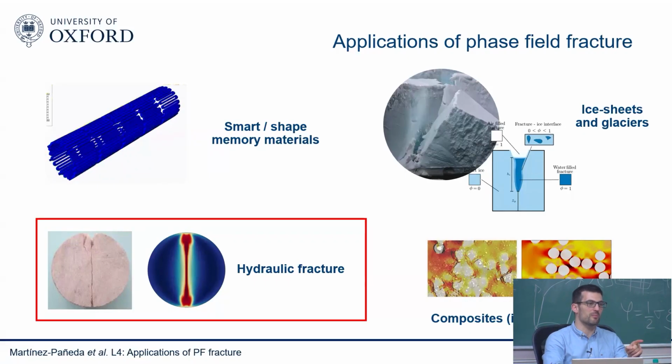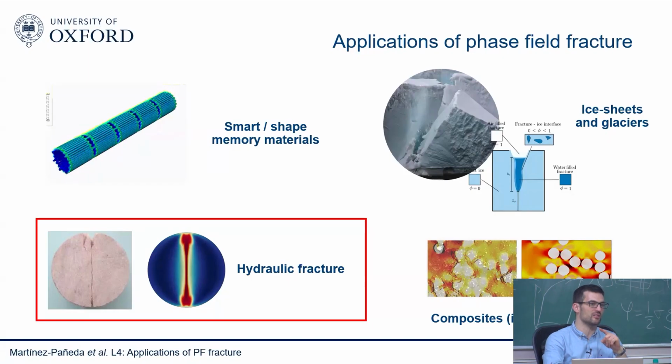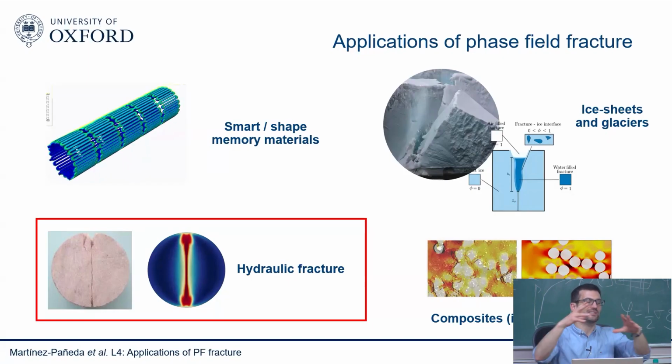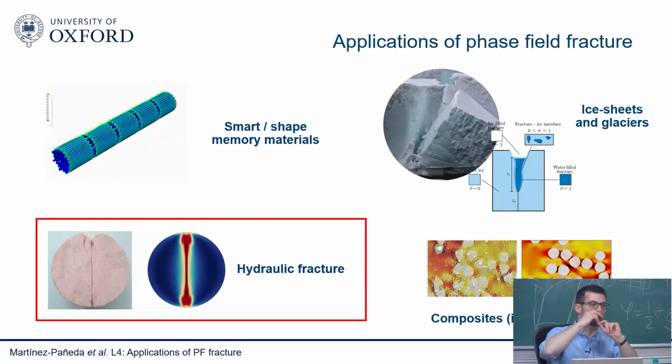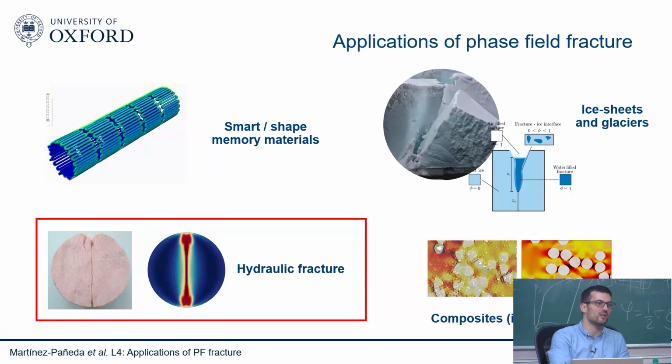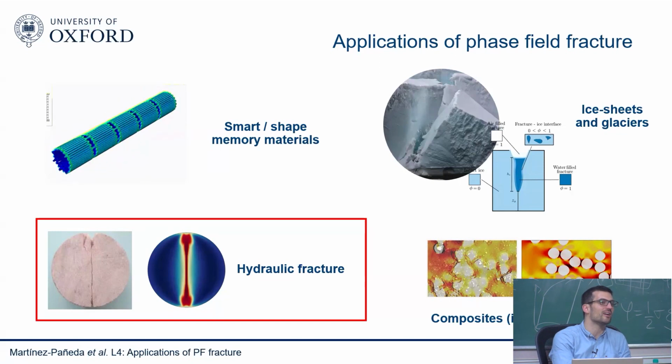What we're saying to people is that if you do linear elastic fracture mechanics analysis, make sure, because the strain state is such that creep is dominating, to pick your Poisson ratio to be equal to 0.5 to capture these stress fields that come from this incompressibility, as opposed to the ones that will come from a linear elastic material with 0.35.